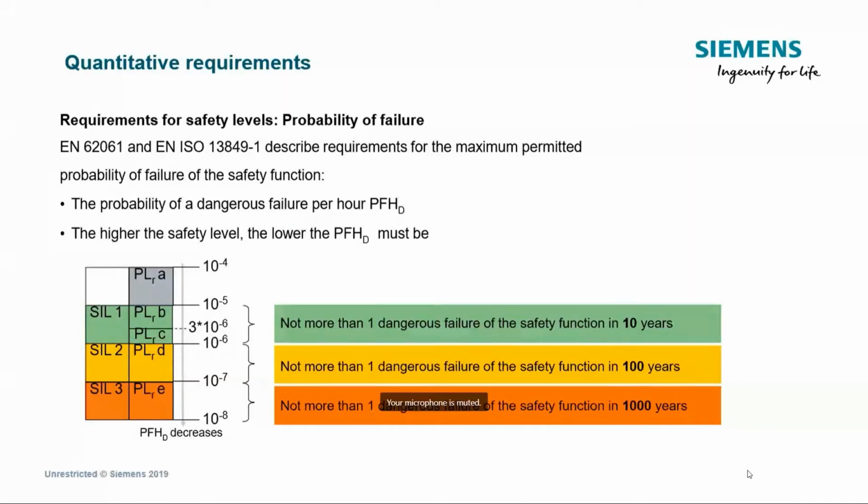So, this is another term that you'll see quite frequently when you're designing or selecting a safety system. It is a number or figure provided by the manufacturer of the particular device that gives you an idea of the probability of a failure or a dangerous failure over time, normally per hour. And it's also a criteria for you to identify that a particular system is according to, say, SIL 2 or SIL 3 level, performance level D or E.